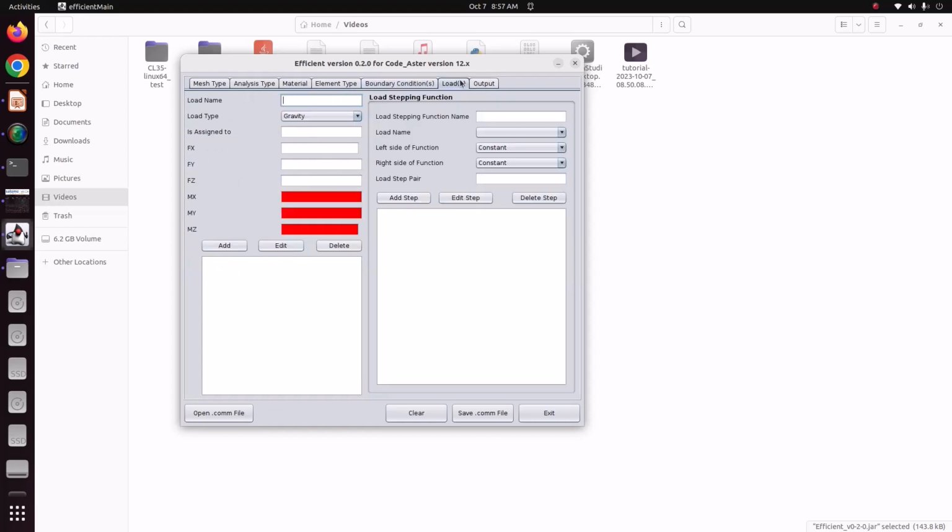Now we just want to apply load. So go to load. Here we can choose pressure and force. Both will apply as a pressure only. The only thing is, pressure has only a positive and negative value. If it is a positive value, it is a compressive pressure. If we are giving a negative value, that means tensile pressure. If you are using a force on the face, it will also apply as a pressure only, but it has a direction. In this case we are going to apply a compressive load. Anyway, we can use pressure. I'm just going to use pressure.